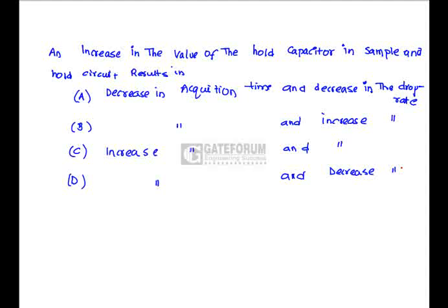See, if we increase the hold capacitor value, the time constant is going to increase, which will increase the acquisition time as well as decrease the drop rate. That means option D is correct.